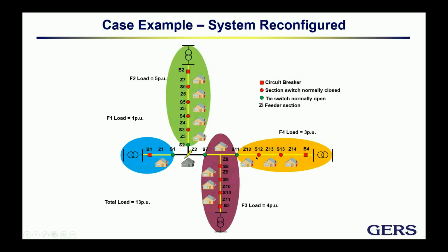In terms of relay pickup, that means that feeder 1, of course, doesn't have any trouble. Of course, if it was handling 14 sections, it can handle 1 without any trouble. But feeder 2 went from 3 to 5, that means an increase of 67%. Feeder 3 went from 2 to 4, 100%. And feeder 4 went from 3 to 4.